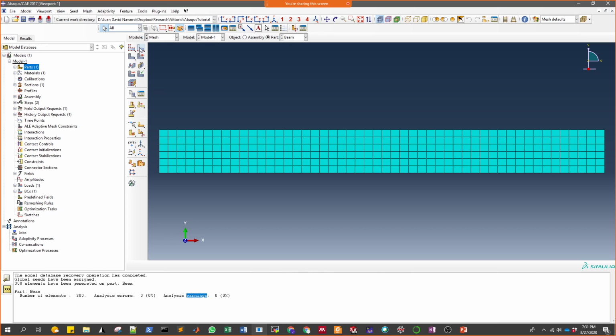Second, try to change the seeds in the edges of your domain. Having control on how many elements you want along a curve or along a line might help the mesh a lot. And finally, if none of those work, then change your element. Instead of using square elements, maybe you will have to use triangles, and there's nothing else that you can do. Those would be my suggestions.